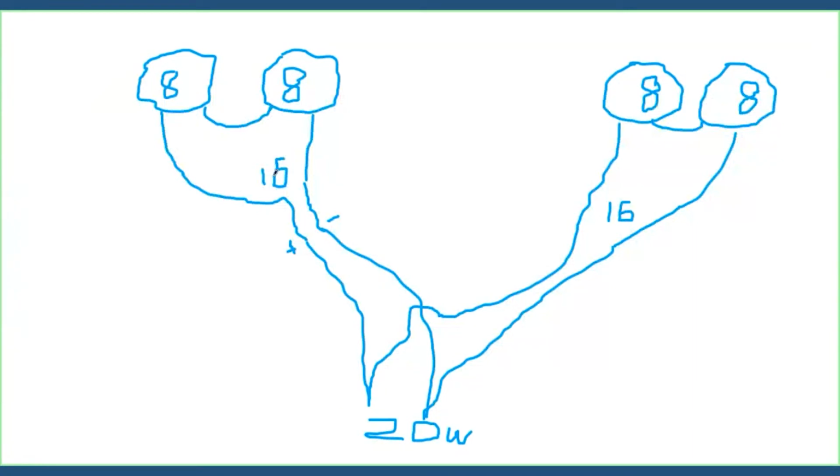And so if we divide 16 by 2, we just drop the total resistance of this circuit down to what? Back down to 8 ohms. So we used a combination between two separate series circuits, but then wired the two series circuits back into parallel.